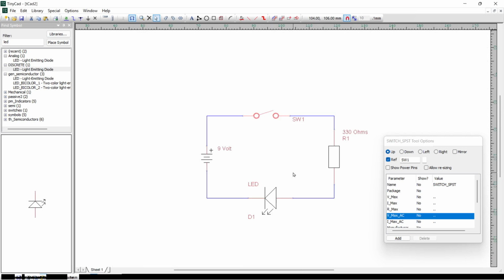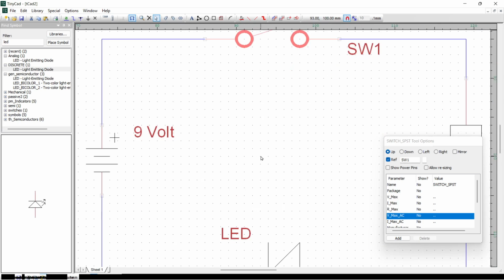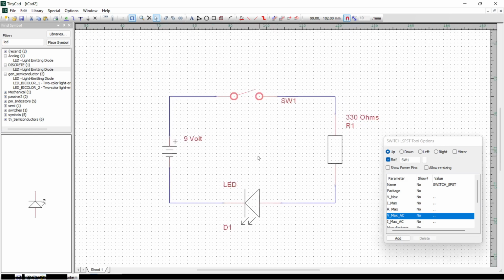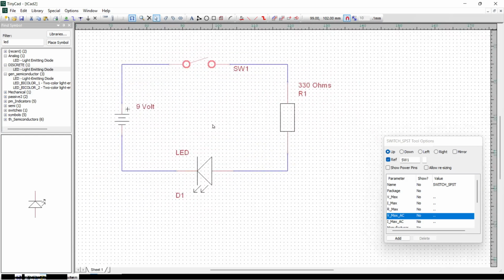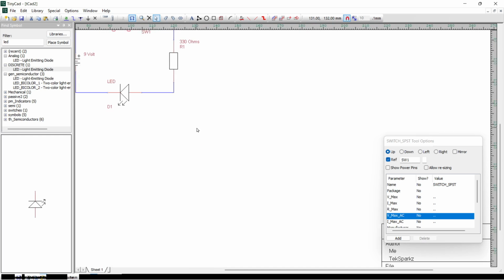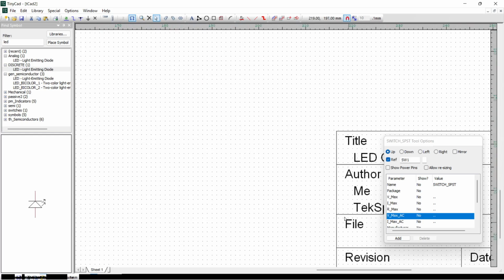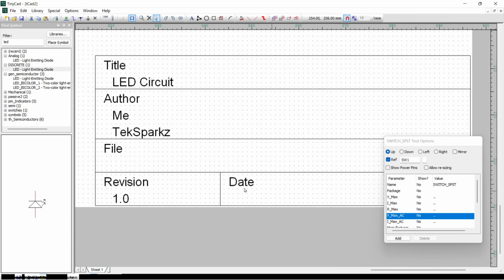And then what will happen here is if we zoom out of our drawing, I'm using the mouse wheel, by the way, to zoom in and out. Roll the mouse wheel forwards, zooms in, roll the mouse wheel backwards, zooms out. And then you can use your right button. When you hold down the right button, you can move the diagram around. So I'm just going to zoom out, and then I'm going to go and have a look at what's in this part, and you can see that the details area of the drawing has been filled in based on the design details we put in.